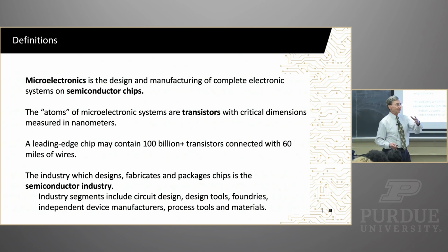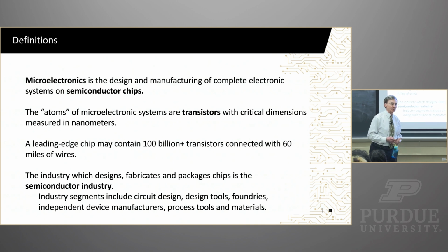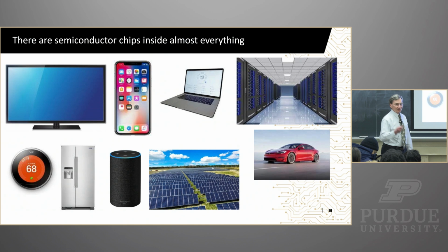So you talk to people about the semiconductor ecosystem, and they mean all these things that tie together, where you can be at one end. These days, in your garage, you can design a chip, and you need some cash to do this, but you can actually have a foundry build that chip for you, and some other company package that chip for you, so you can get in the game without spending the tens of billions of dollars it takes to set up your own chip fabrication facility. Companies like Global Foundries will gladly, for a modest amount of cash, do that fabrication for you, right? And they have the infrastructure and the design kits and all that to make it work.